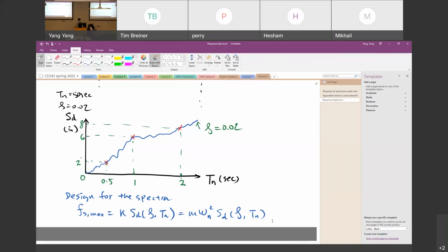So any questions up here? Yes. This is just a general question. The damping ratio of a structure, is that like the stiffness? A very good question. The damping ratio is different from stiffness, because for stiffness we use K to reflect the stiffness of the structure.